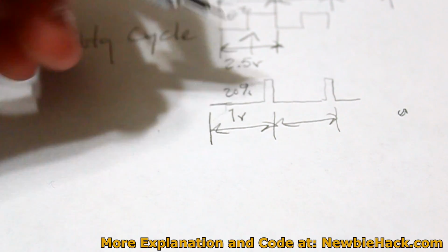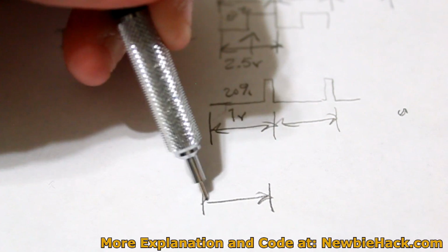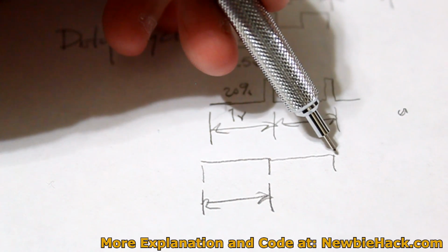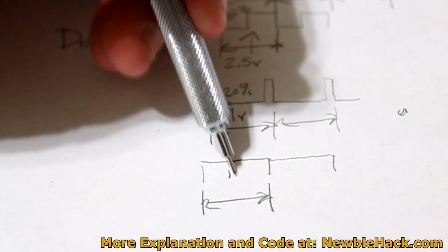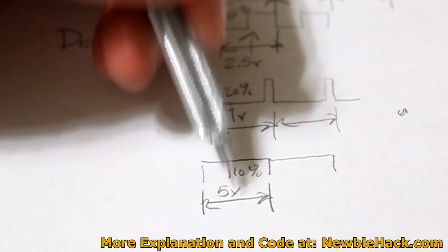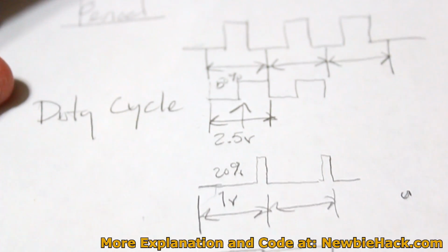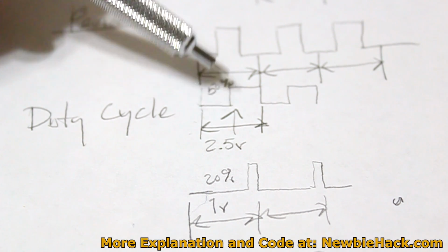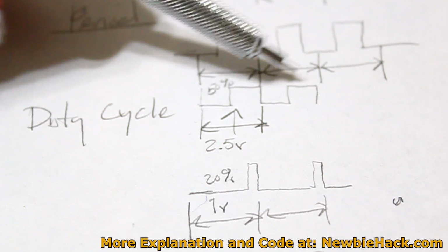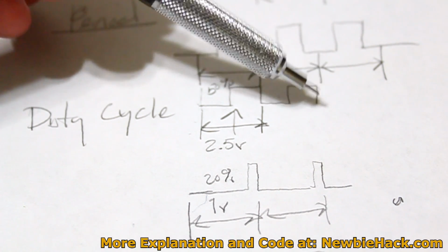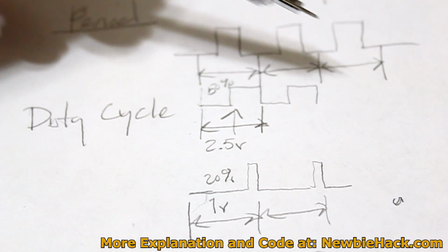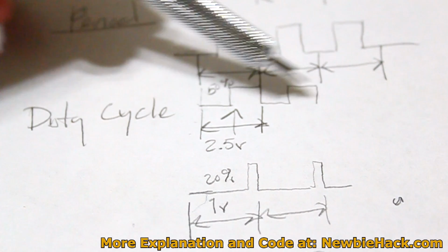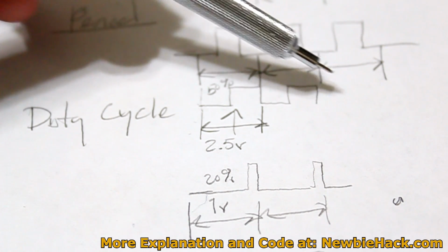And if we had a 100% duty cycle in this period, essentially you'll have the period constantly on. It would constantly be 5 volts all the way through. So 100% of 5 volts is 5 volts. Now we have a couple of options working with PWM. When we're working with servos, if you wanted to feed a servo PWM, we could just give it to the servo just like this with these pulses, and it works perfectly fine just getting pulses. But some other more analog devices might not really appreciate pulses, but a nice straight line of voltage.